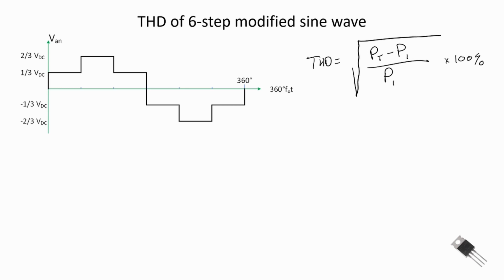For these calculations, I'm going to assume a resistive load equal to 1 ohm. And it will normalize, because if I do the power calculations, there'll be that term in the numerator and denominator. And so really we'll be looking at just the voltages. So to look at the power total referenced to a 1 ohm load, I really just need to look at the voltage squared.